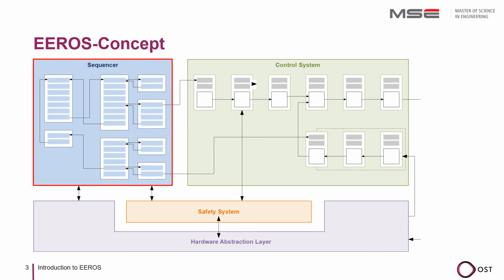The sequencer ensures that work steps run strictly sequentially, as the robot movements must be executed strictly one after the other. If an unforeseen event occurs, the current movement must be stopped and exception handling takes place. The safety system is designed as a series of hierarchical safety levels. It monitors critical inputs and outputs and ensures that a fallback to the emergency safety level will immediately and reliably cause the robot to stop, regardless of who or what triggered the emergency event.